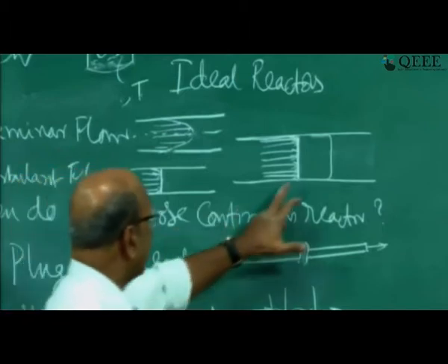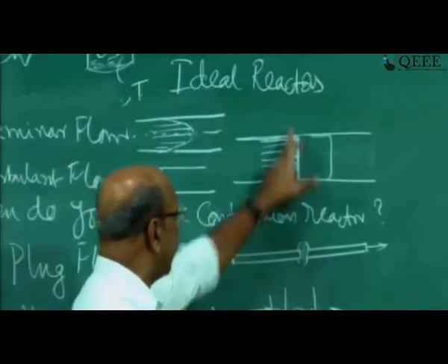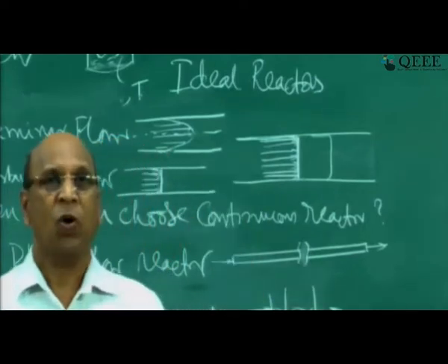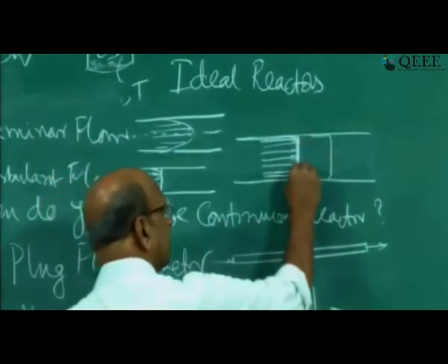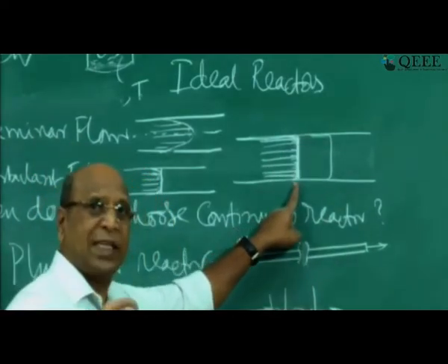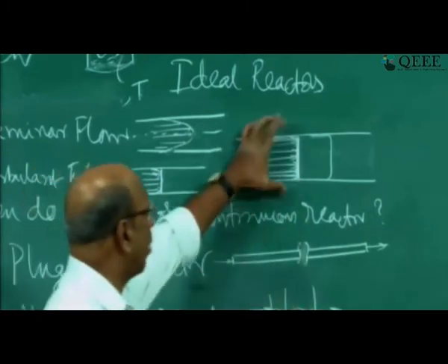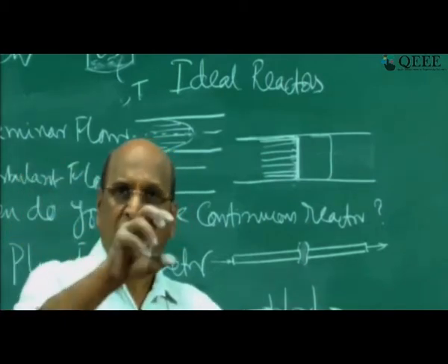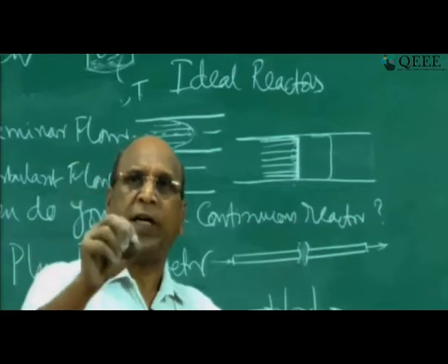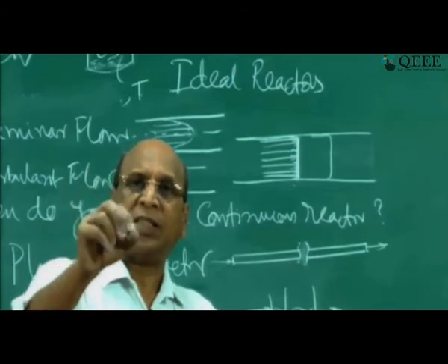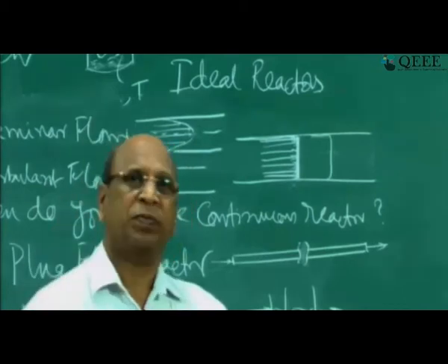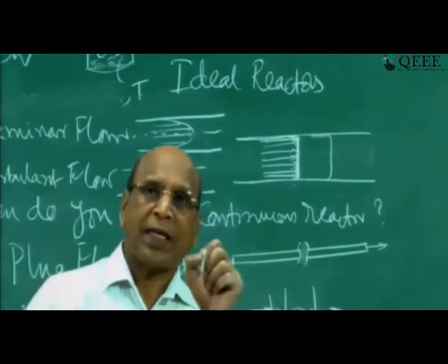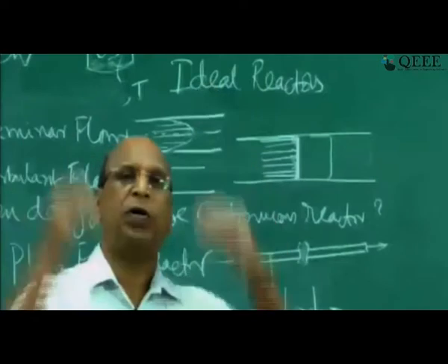Okay. So that is why here the ideal plug flow condition will be that each and every particle must spend exactly same time inside the reactor. For that you need this kind of profile. That profile to exist in reality is impossible. You should not have walls at all. And we know that fluid mechanics, when you recall, whenever you have a pipe and then flow, whether it is gas or liquid, always we take this no slip condition where the velocity on the inside surface equals 0, right. So when inside surface the velocity equals 0, those particles which are sticking to the reactor, it may take infinite time.